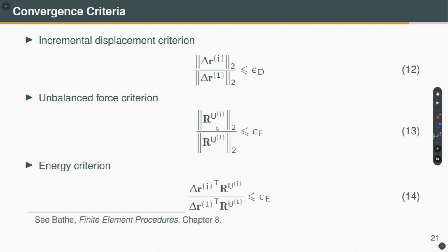Okay. But there are problems with this, because what is the unit? So, when you have the displacement vector, you have translational degrees of freedom as well as rotation. So, they have different units, right. When you take the L2 norm, you cannot handle the units, because what is the L2 norm of a vector? It is the square root of the sum of squares. Okay. So, similarly, there are problems here. So, you may get good results for one force quantity, let us say axial force, but may not get good results for moment. Instead, if you use the energy criteria, what is the energy criteria?